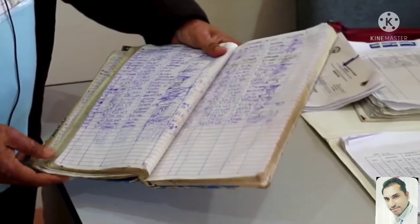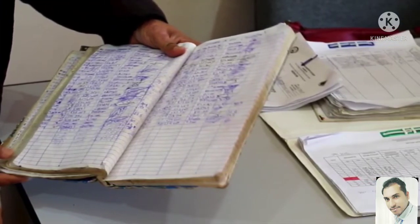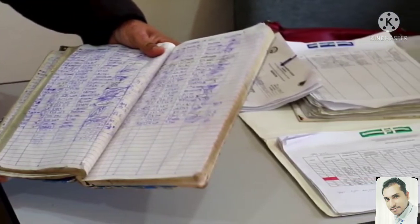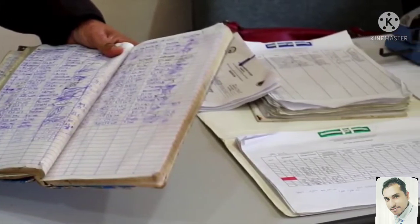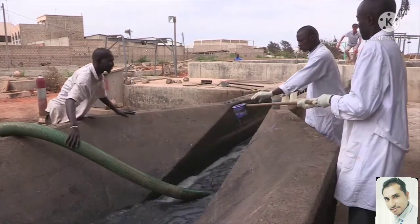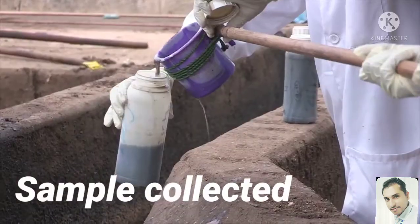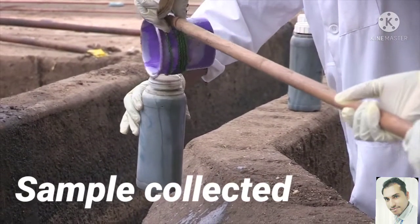Monitoring, for example, includes records on the sludge volume that is discharged at a treatment plant. This is important to assess whether the treatment plant receives more or less sludge than designed, and this will affect the performance of the treatment plant. In addition to records on the sludge volume, characteristics of fecal sludge discharged at a treatment plant and of treatment products from treatment technologies can be used to estimate the treatment's performance.